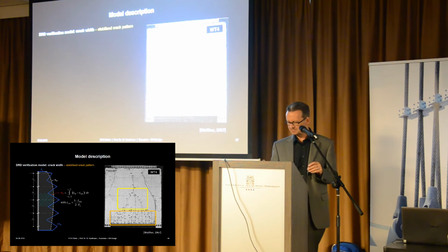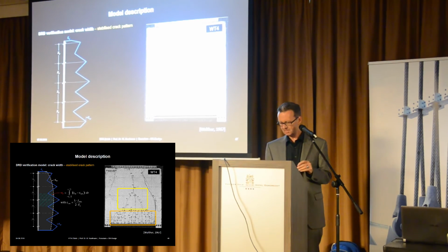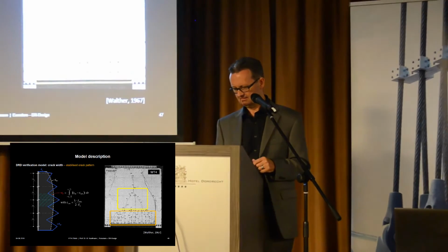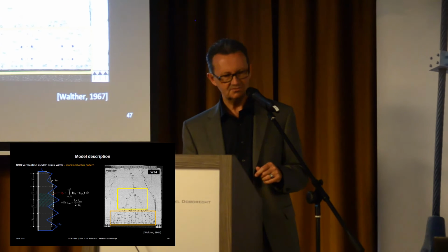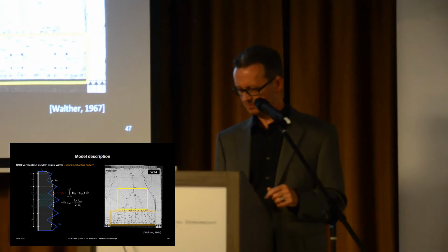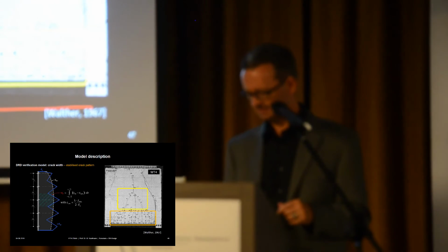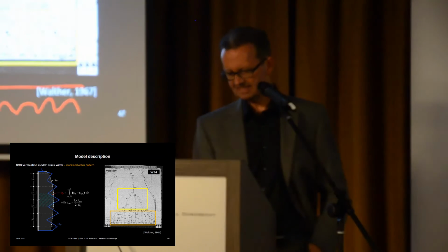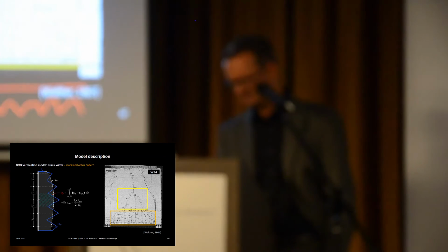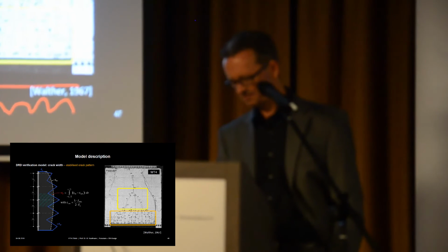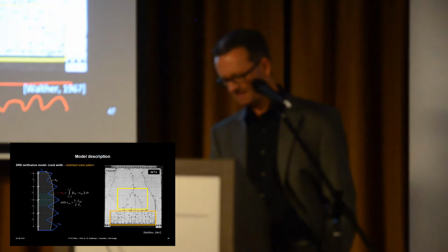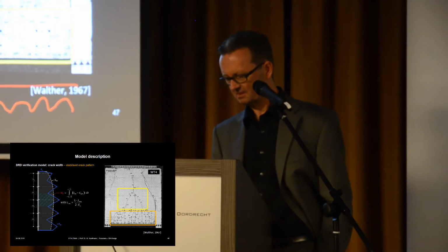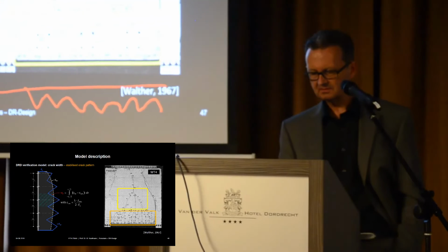Now looking at the test here by René Walter, carried out in Stuttgart. So if you look at this tension chord, probably it was the format of the slide, so this one here should be down here with the cracks being shown here. You have to turn it around. So the steel stresses and then also the steel strain will be highest at the cracks. So these are the cracks here. You get the highest stress and also the highest strain there, and in between it's a bit less. So how do I calculate the crack width?